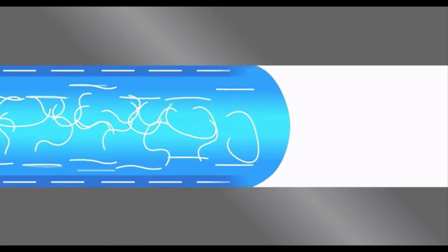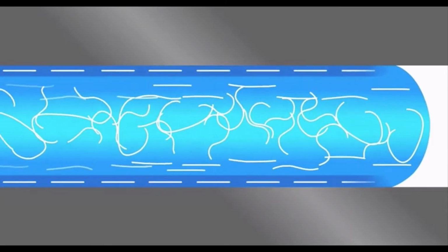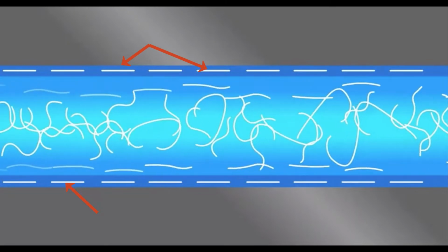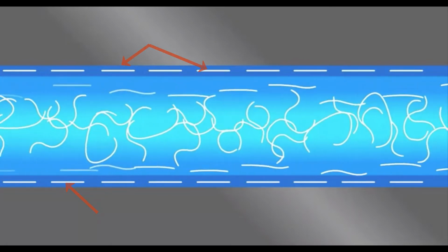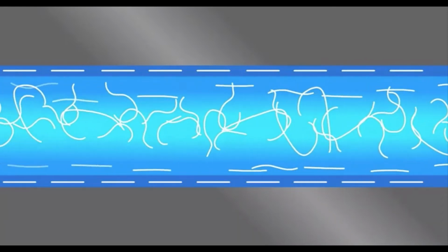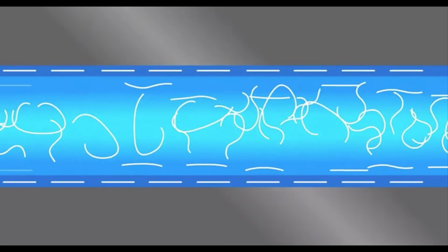The shear stress experienced by the material as it flows orients the plastic molecules in the direction of flow. The molecules at the mold wall are the most aligned, as they experience the most stress, and least aligned in the center. As the part cools, the orientation is frozen into the part. The orientation of the plastic molecules is important as it will impact the part warpage.